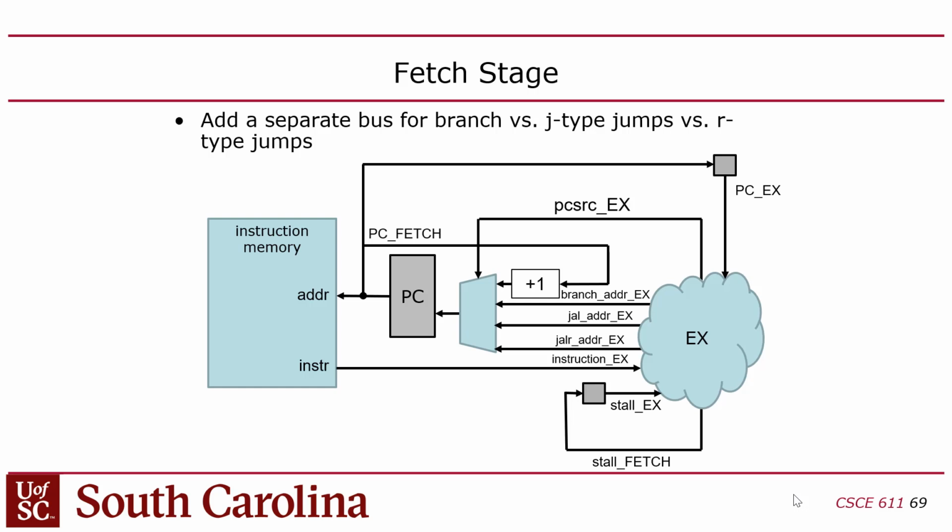Does that make sense? Now you have to be very careful because now you have an output called stall and an input called stall, and you've got to make sure that you've got that register that breaks that path up. Because if you forget to put that register in there, which in this class usually a few groups will do, you'll end up with a combinational loop, right?